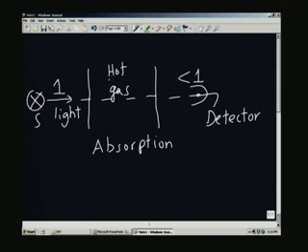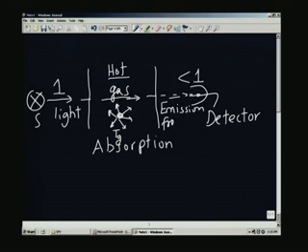Now, imagine that the gas is hot. So, the gas molecule, suppose you take a molecule here, it is also emitting in all directions because of the temperature Tg. The gas is at temperature Tg and it is emitting radiation, and therefore, some of the radiation which is going in this direction from the gas molecules within will also be coming here. So, we will say emission from the gas. So, plus that, less than 1 because the light which is leaving the source here is reduced because of the passage through the gas, but plus emitted.